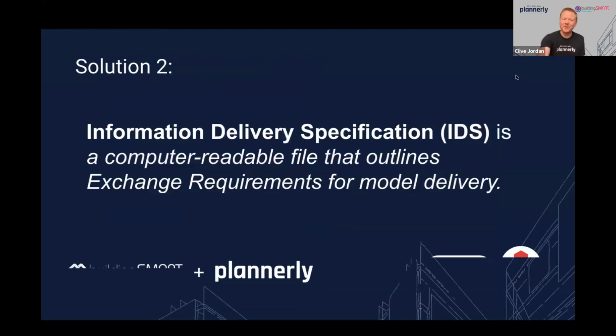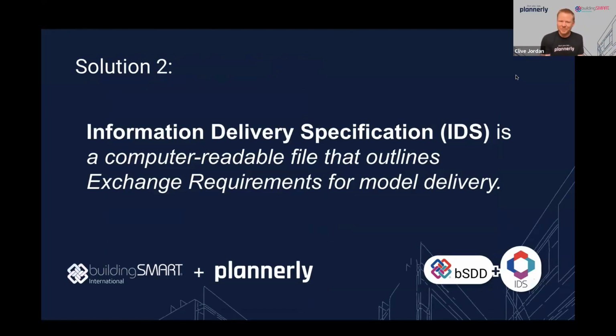Absolutely. So in step solution number 2, the IDS. IDS refers to an information delivery specification. And the reason why we need to standardize not just the properties and the classifications, we can use those to create lots of different spreadsheets, as we were saying, that might be that you can read a file, but it's not in a machine readable format that's always the same way that can be relied upon.